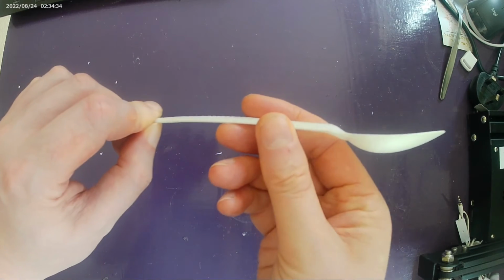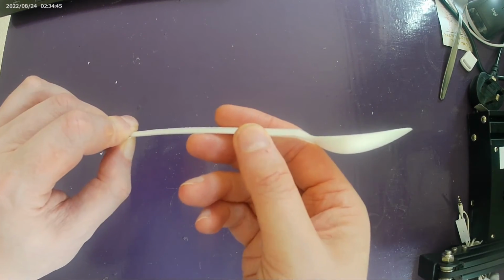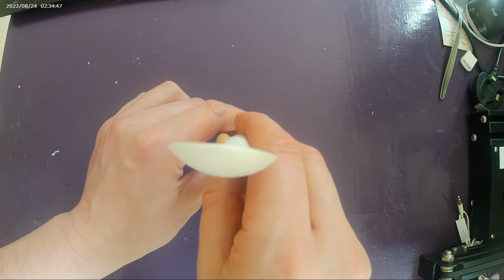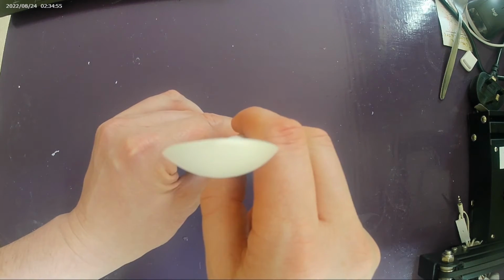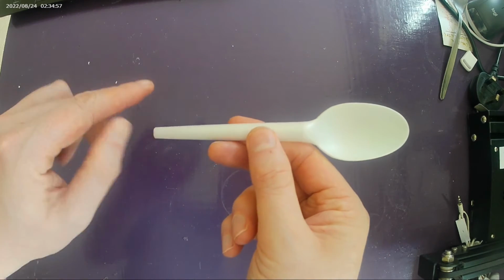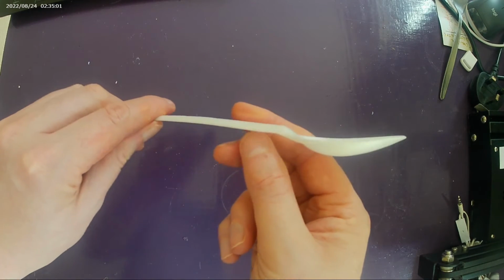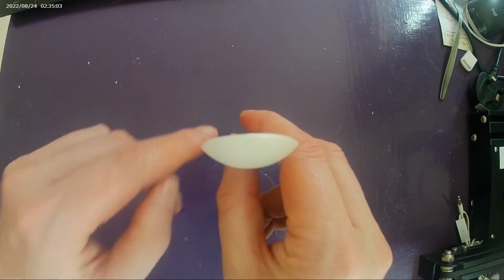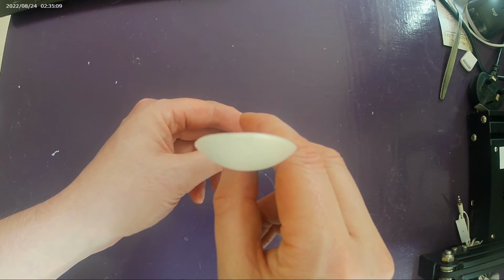We can create a profile going along this way, which will be a path for a sweep, and create curves this way going along here. It will still be a rectangle. So look at the bounding box. So it still will be a rectangle, but we'll have the curvature there that we can create the intersection with.